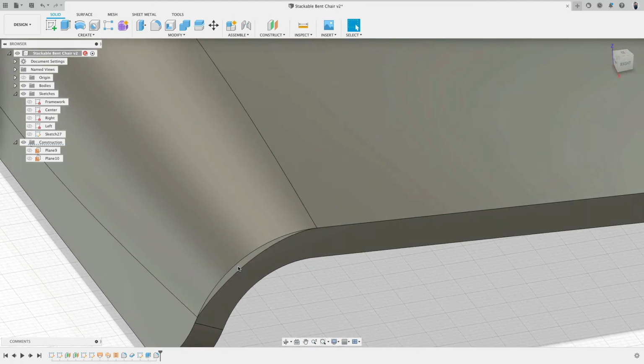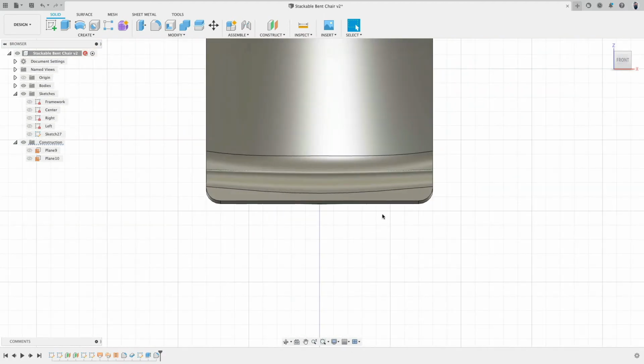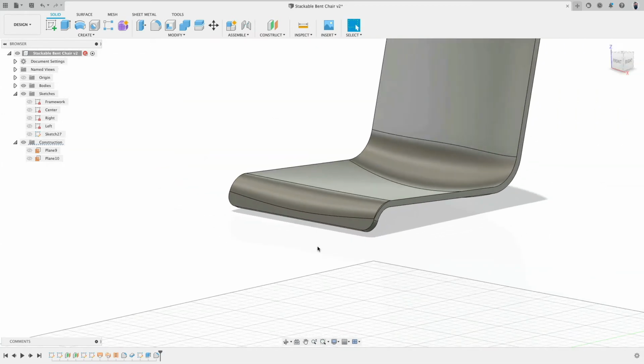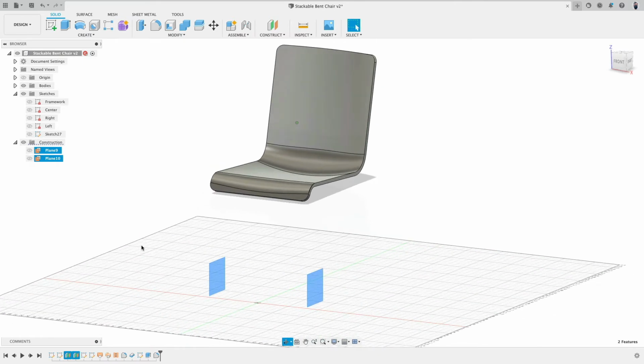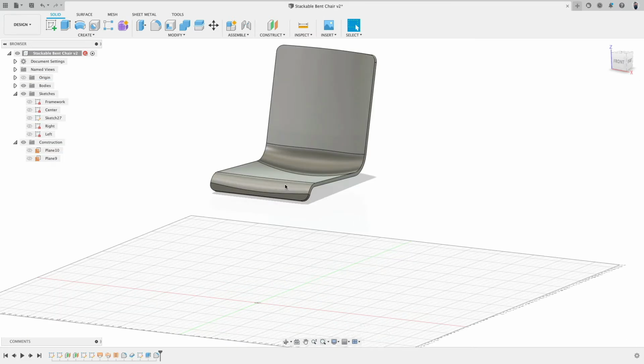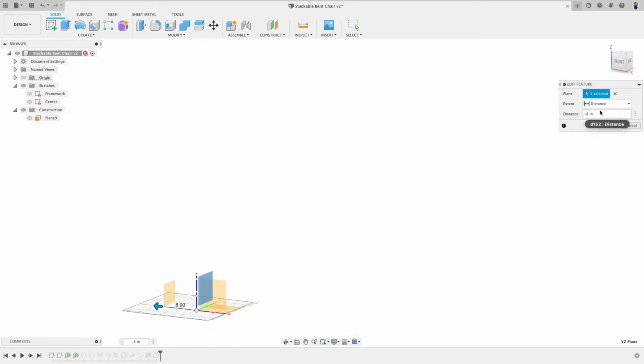Close. You see, there's a little bit of a facet. So what do we do? We have this really at 16 inches and it needs to be smaller. Well, then we make the piece smaller. Well, the trick here is actually super easy. These two construction planes, we simply make a tick wider. Maybe it's just 8.1. Not too much. Let's see. Yeah, that did it. So then we do the same on the other side.